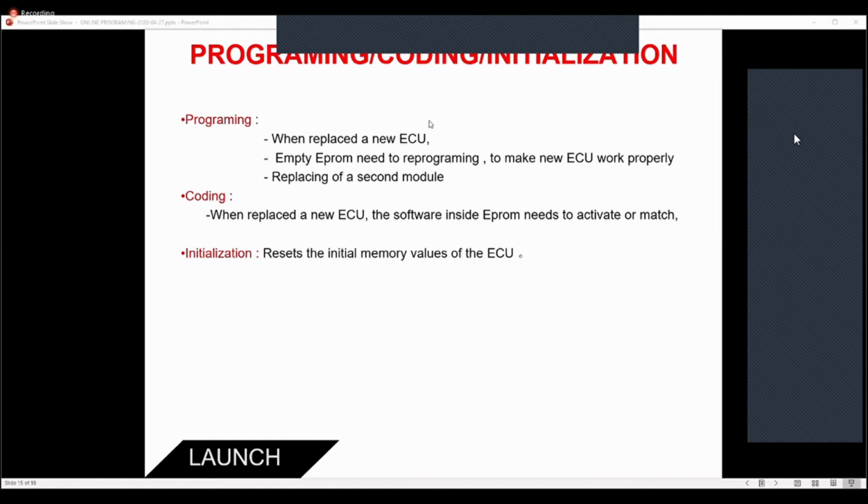After you do all this, you may have to initialize the ECU by turning the key off or taking it for a drive. And in some cases, some of the modules, like foot modules, you activate the windows up and down or lights on and off, and that initializes the program to make sure it works.